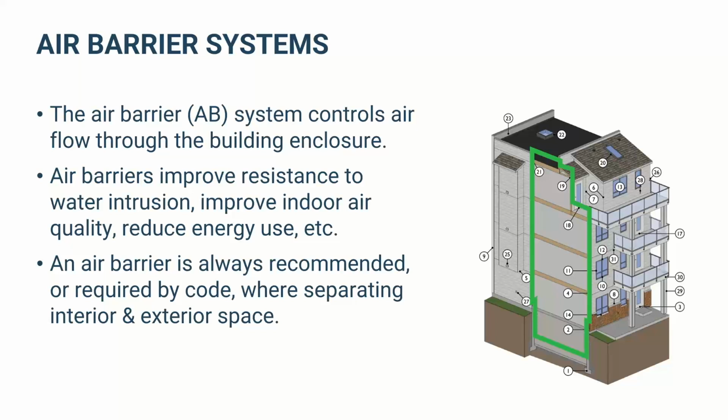So anytime you're separating interior and exterior space, you need to have an air barrier. It says always recommended or required by code. I believe it now is required everywhere by code, at least in North America, or I should say Canada and the US. It's required everywhere, and it's not going anywhere. So we need to have air barriers.